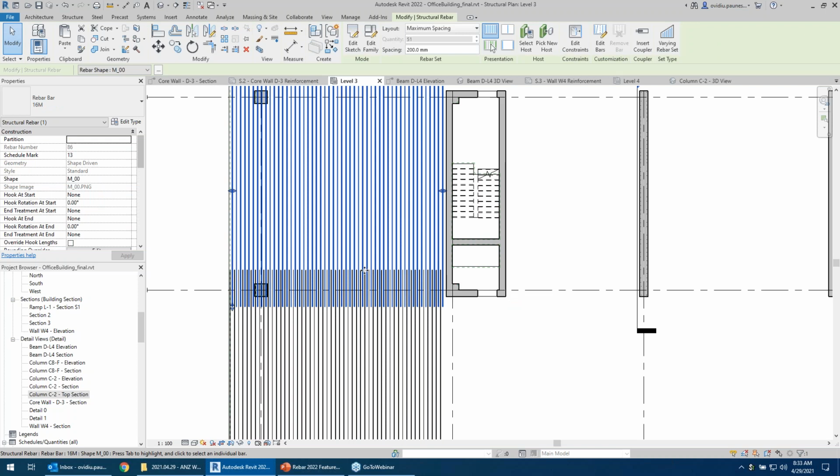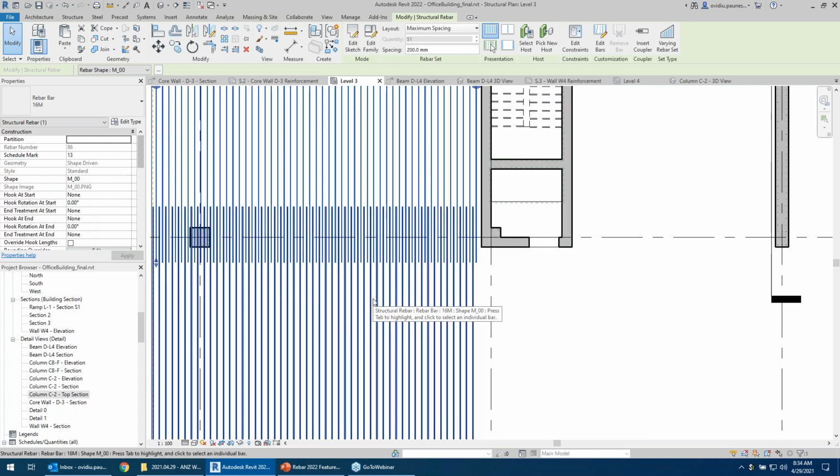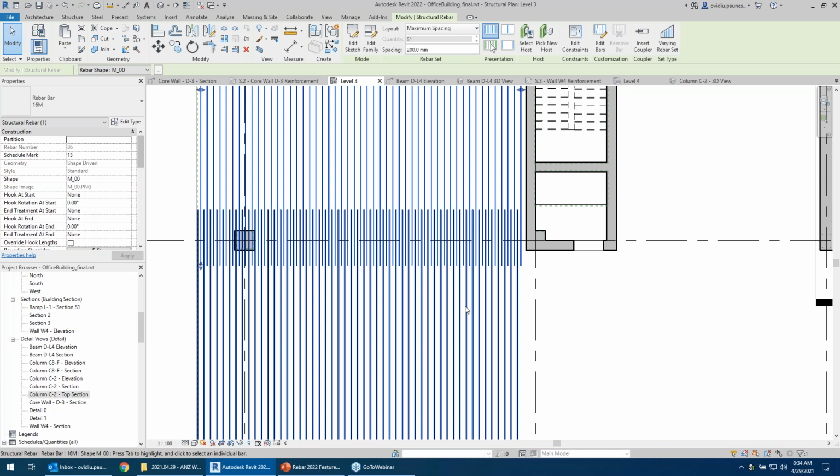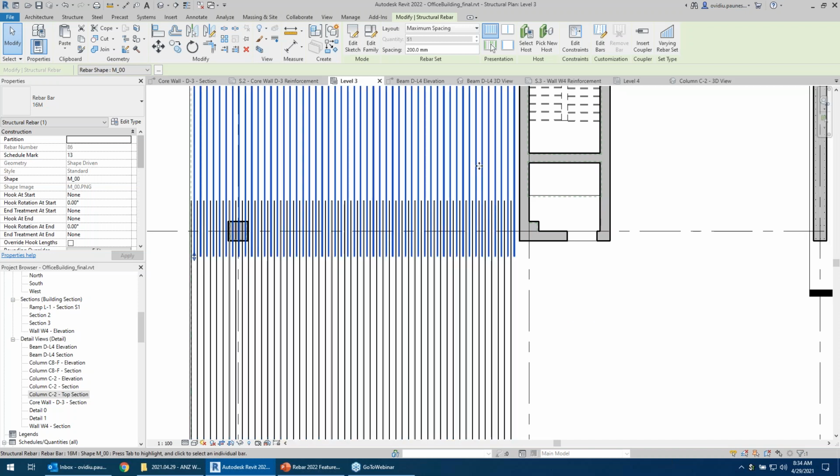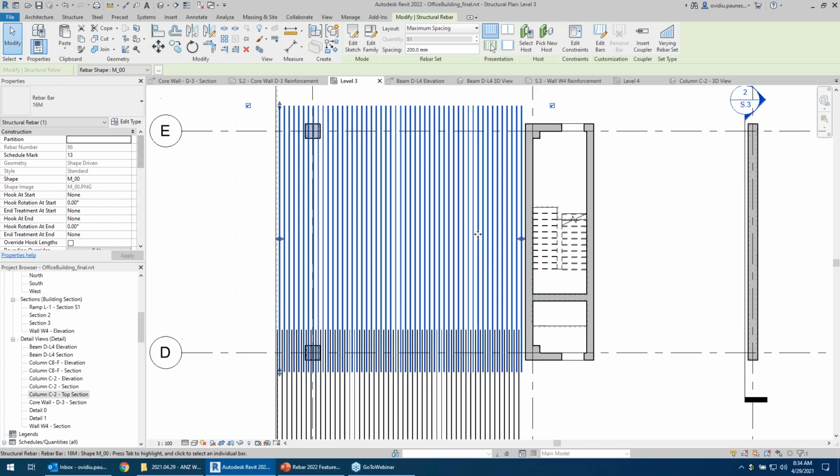So in Revit, as you may know, rebar reacts to the changes in the host. It connects to the concrete faces and it follows those faces when they are modified or moved. Since Revit 2020.1, there is also the ability to constrain any rebar together, so one rebar to another. And where this is useful in our particular example is to maybe define the splice length. So if I take the bottom bar and I would like to